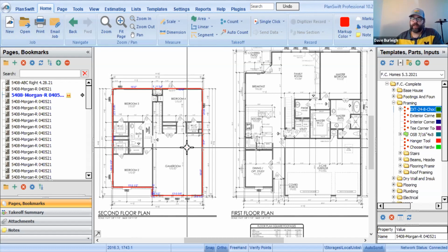So what we do differently today than we did even up into late 2020: in the old days, we as estimators would say that's a 2x4 exterior wall at 16 on center, and we just got a total lineal footage of those. And within that lineal footage, we had factors to say, you need a stud every so many feet. And it got you close, but the problem is it didn't take into account what happens when I break my bottom plate. Now I'm going from one 16-foot section to the next. Now I need an extra stud in that location to close off both of those wall sections.